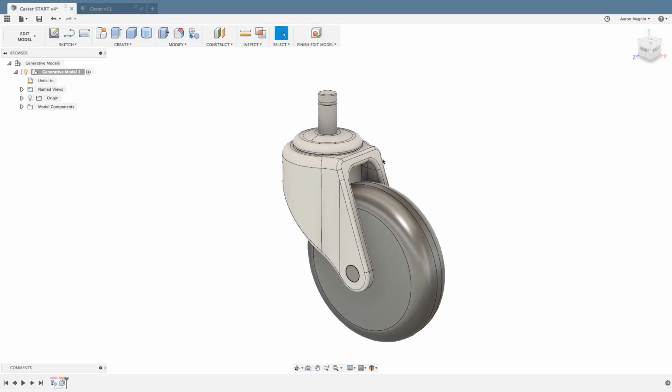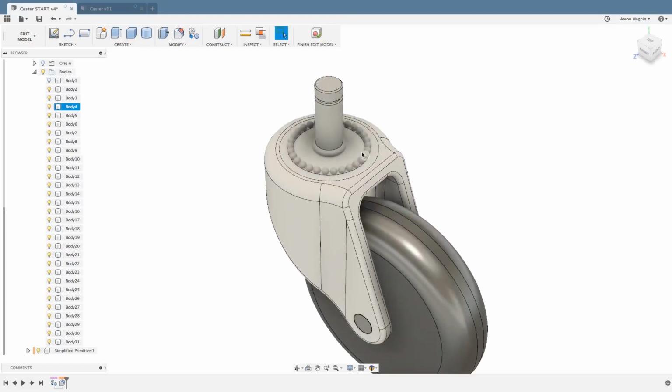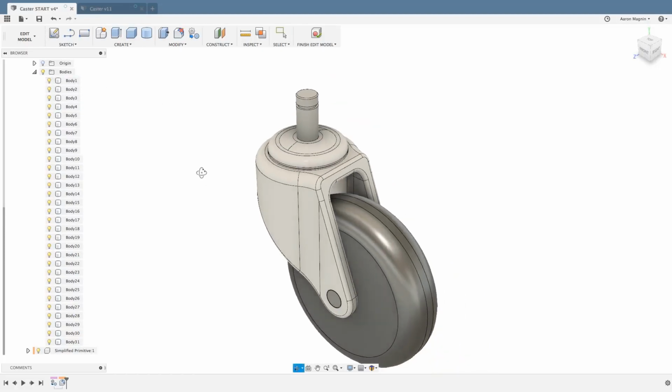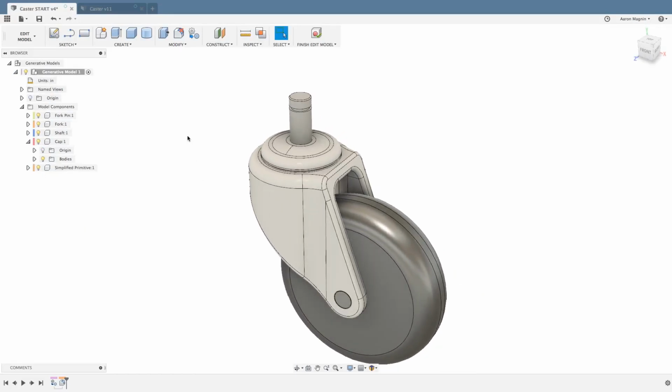In addition, at the top of this, there's actually this cap, but within the cap itself, there's a bunch of different bodies, and I'll just hide the top body on here. You can see there's actually all the bearings, the bearing wheels that go along with this to enable us to slide freely. So again, I don't necessarily want all that detail. I do want to make sure to preserve that area though. So we'll do something here again. We'll just do a replace with primitives.